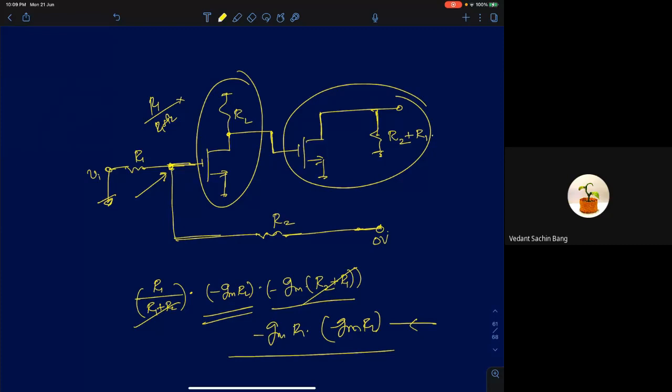So that's it. So we saw how to analyze and find loop gain for negative feedback circuits. One important thing we said was that in negative feedback circuits, since the loop gain is a dimensionless quantity, whatever be the circuit, voltage amplifier, current amplifier, transimpedance or transconductance amplifier, you can just break the loop at some point and apply a voltage and find the voltage at the same node after traversing back the entire loop, and the ratio of the two voltages will give you your loop gain.